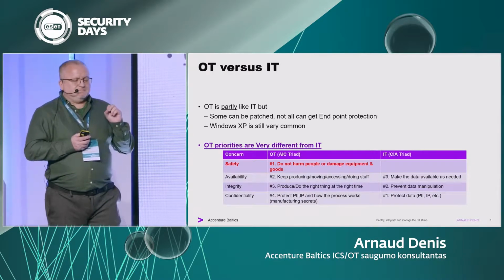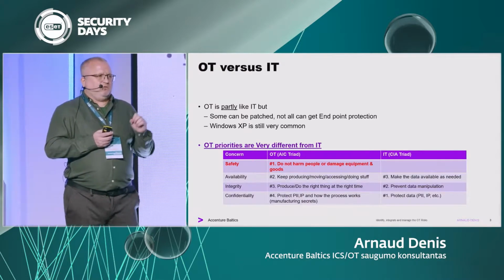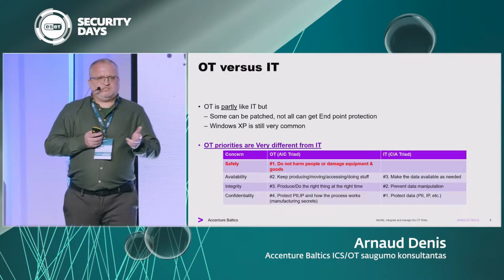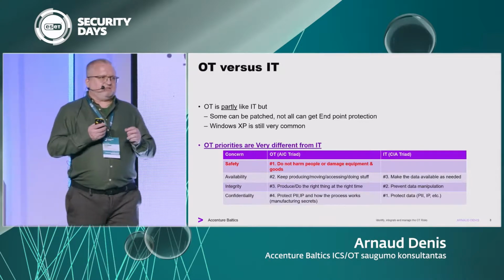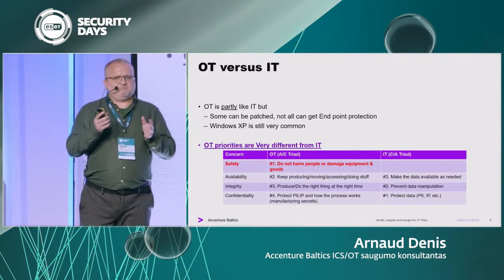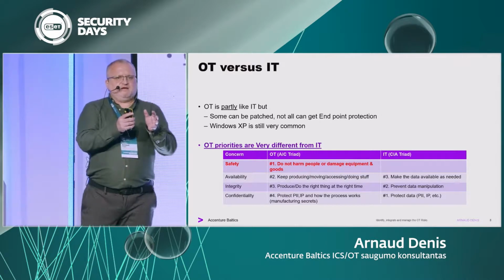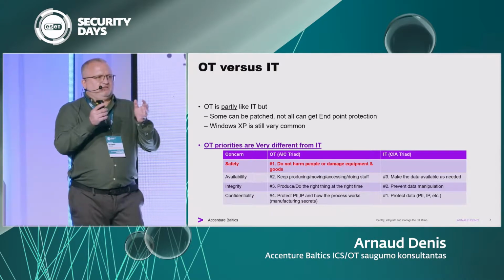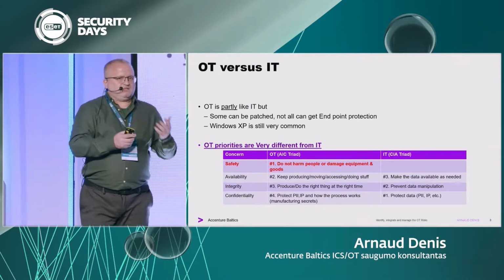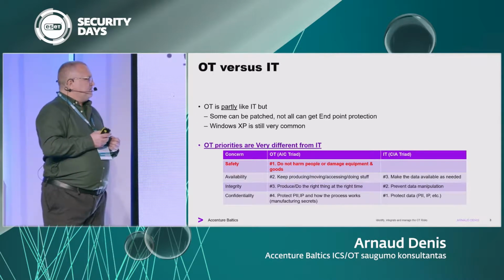The other thing is, OT always follows a need for form factor, fit, and function. Changing an equipment in OT might mean that you need to change more than that, because it has a spatial size. It fits exactly in there. If you change your equipment, you're not going to have the same size. It's going to be deeper. The cables are not going to go. There's going to be all kinds of problems. So you always need to look at all those things.